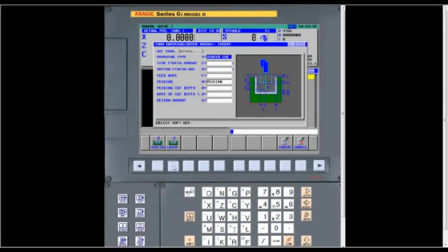If you want to use layering, it only takes layers out. It'll go down so far, rough it completely out, go down a little further, and rough it completely out. That's how that works. But if we use center cutting, then you can leave a certain amount of finish stock. You can see both of these next two fields have asterisks, where you don't have to answer that information. You can set a feed rate and a pecking, where it goes in so far, backs out, and breaks a chip.